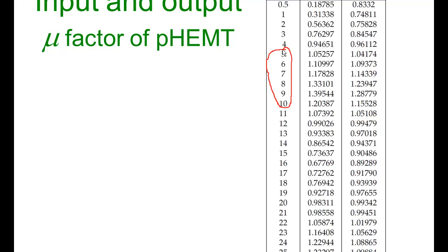We're going to see that if mu1 is telling us that the input network results in instabilities, well, we'll also have an instability at the output. But the relative levels can be used. In this case, this is saying that if we consider just mu1 at the input, our circuit is going to be a little bit more stable at 9 gigahertz due to the input than at the output. So this would tell us that maybe we want to apply a little bit more attention to the output network. Not a really big deal, but CAD programs do tell us both.